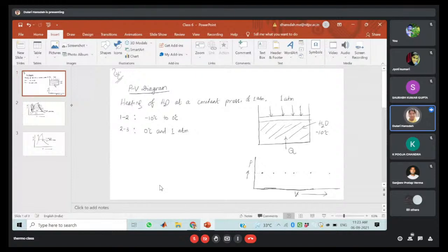In the case of your pure substance, water, when there is a phase change from solid to liquid, there will be a decrease in the volume of the pure substance, which is the peculiarity of water. In the case of water only, this happens during the melting process: the volume will decrease, but for other pure substances the volume will increase. Now at point 3, the condition of the water is liquid, and the phase change process occurs at constant temperature and constant pressure.